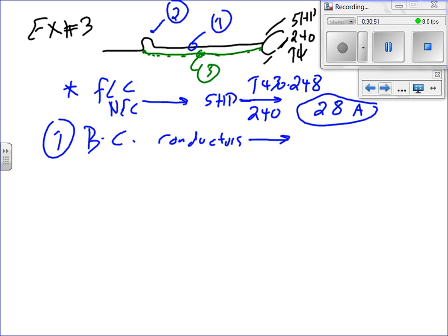For example, if you have an air handling unit or a pump, the pump would be rated for 460 volts and fed from a 480. So there's a difference of 20 volts. Why do you think there's a difference of 20 volts? Voltage drop. If there's up to 20 volts of voltage drop in the system, the machine will still function perfectly as designed.